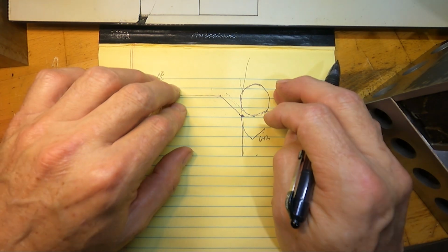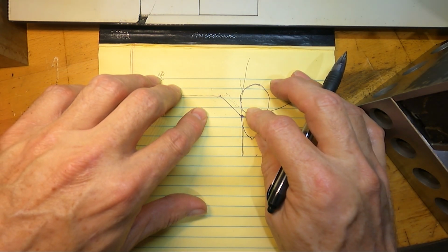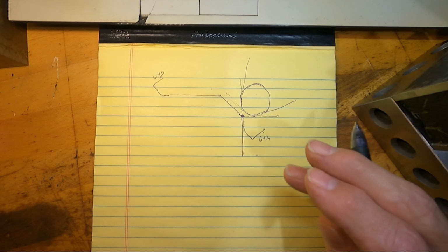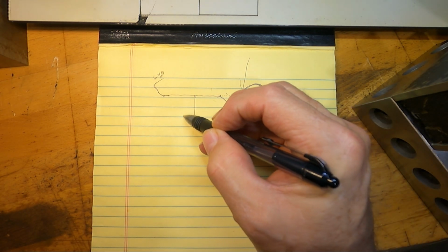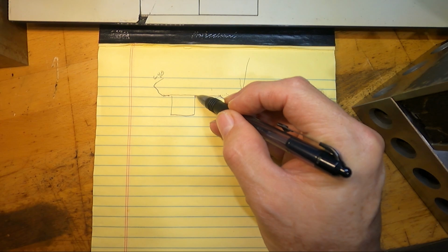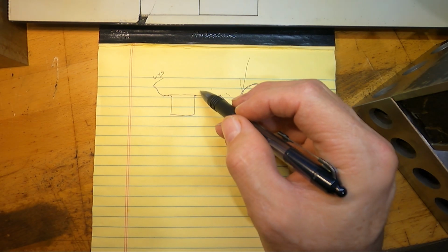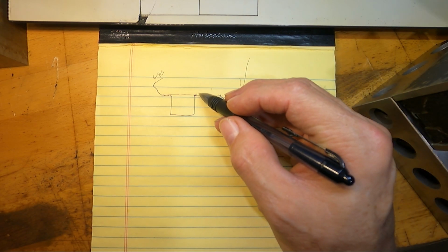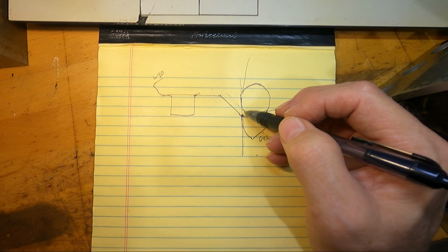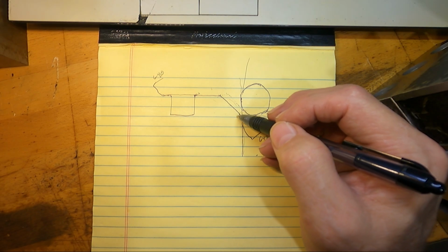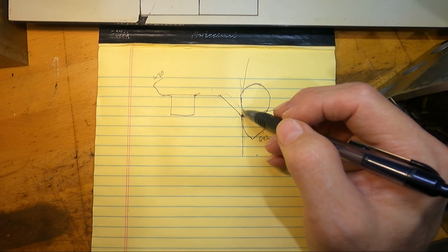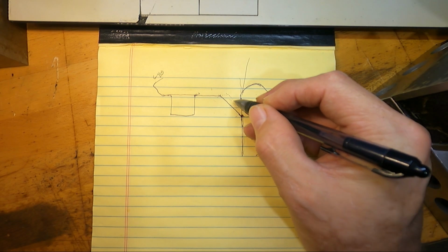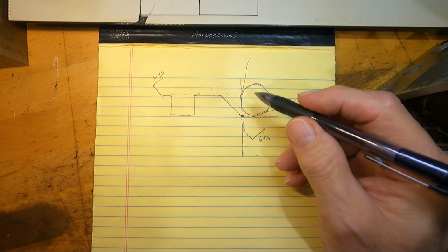So that's kind of what we used to do with it a long time ago, but it still has its uses today for various things, like I explained in the first video about the OD groove, where you're not quite breaking these corners the way you want. You can increase the radius size. So increasing the radius cuts more into the part. As you could obviously see, if this radius was bigger, it would cut more into the part, and decreasing it would stand off the part all the way to the sharp corner here, would follow the line here, but it would be cutting way back here, of course.